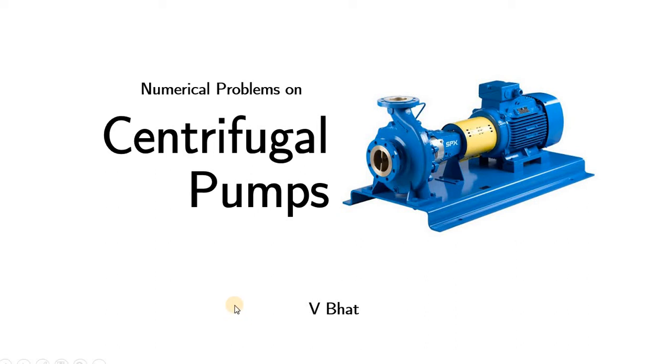Hello everyone. Now it's time to discuss some numerical problems related to the centrifugal pumps. As a prerequisite, for a centrifugal pump, as all of us know, the discharge is radial at inlet. That means alpha equals 90 degrees and hence VW1, velocity of whirl at inlet, would be equal to 0.